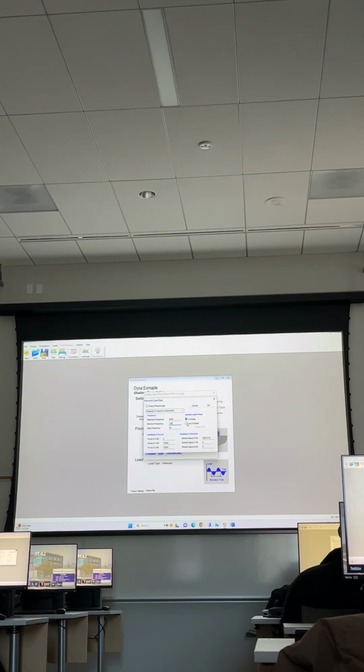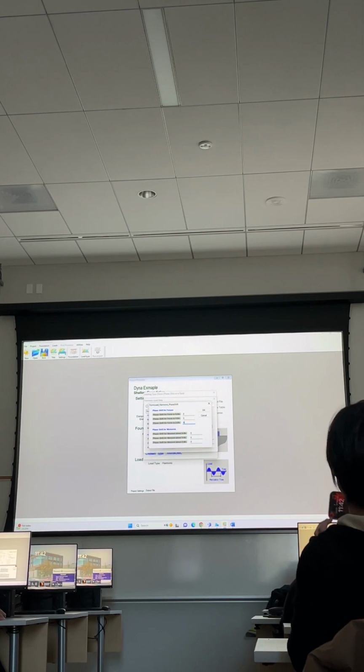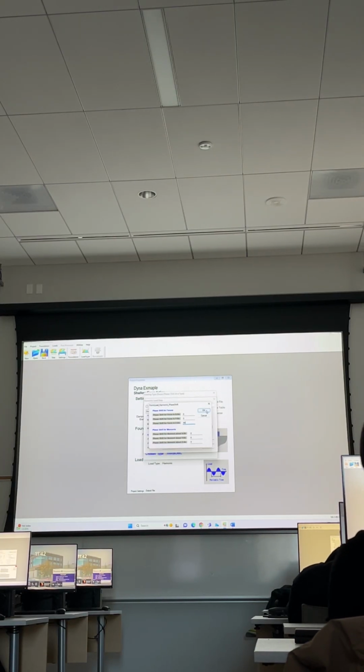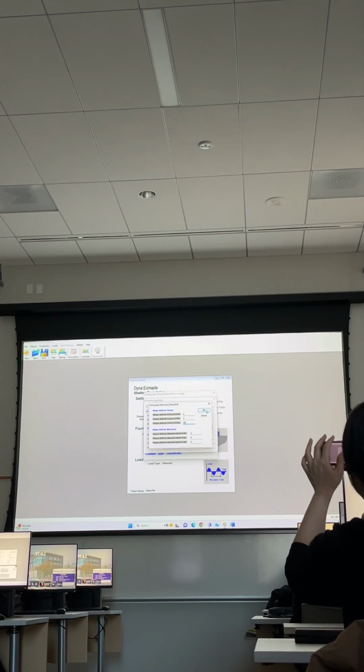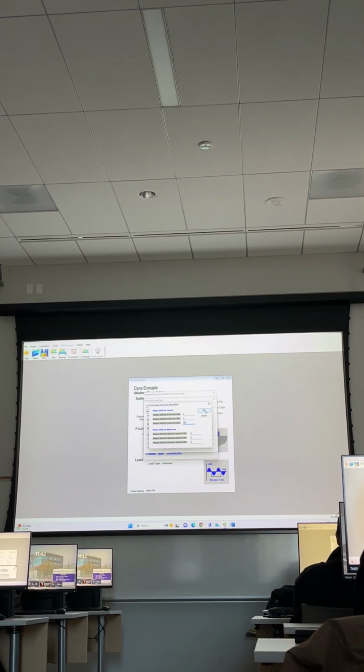So I will choose out of phase here, and we need to choose from here what the phase shift is. For the phase shift, I will assume that it will be in the Z direction, and I will get 90, so it's perpendicular on the other side. Okay? Just note this, this is important. That's how you are telling the software that when the force is maximum in the Y direction, it is zero in the Z direction. Okay? So this is a rotating machine.